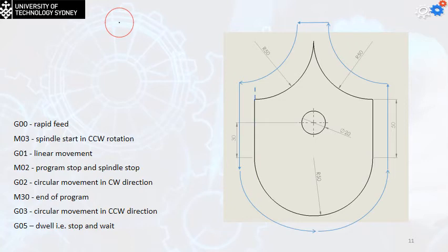So first, I'm going to go up a line equal to the radius of my cutting tool, then I will go to the left with the same value of the radius. What I got here is my center point, the first point of my cutting tool. So I'm going to move to this point. I'm going to use G00 from the home point. I don't have to mention the home point to this point.